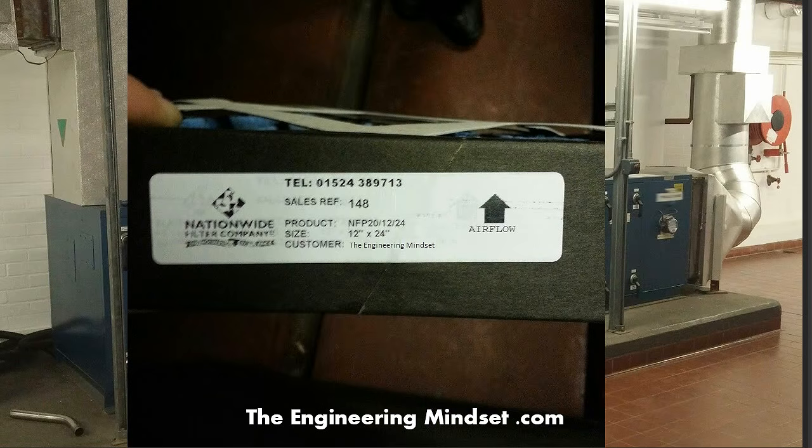You'll also find some information on the side of most of the panels, so you can see the size there. You've got the product description and the company who makes it, but you've got the size of the filter there. This one's in inches, and who the customer is. I've just edited that quickly. But more importantly, you've got the direction of airflow, so you know how to install that within the AHU, how to slide that in so that the air will be passing through this way and out into the supply duct. It's important to get that round the right way.